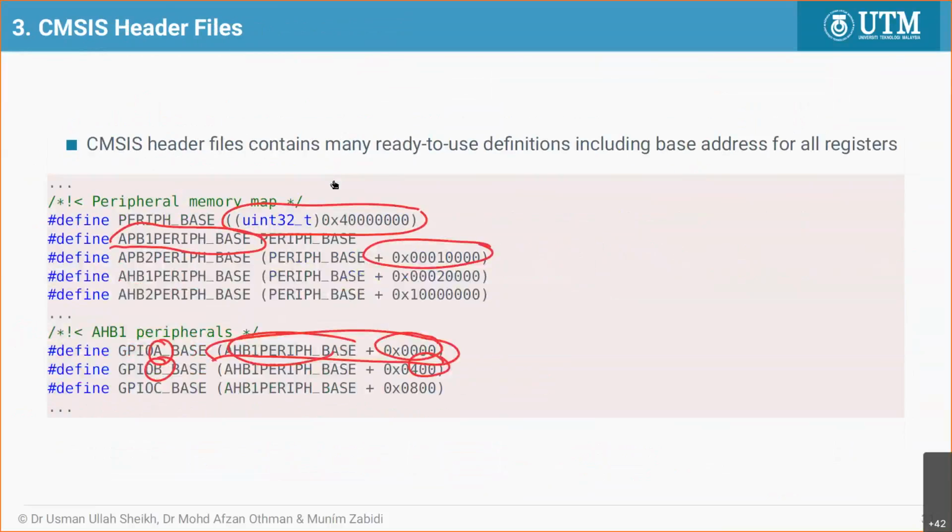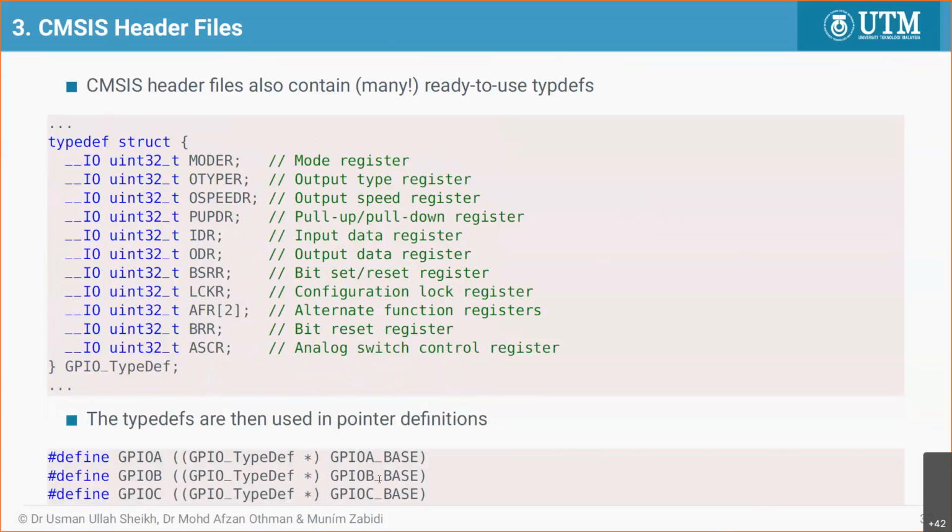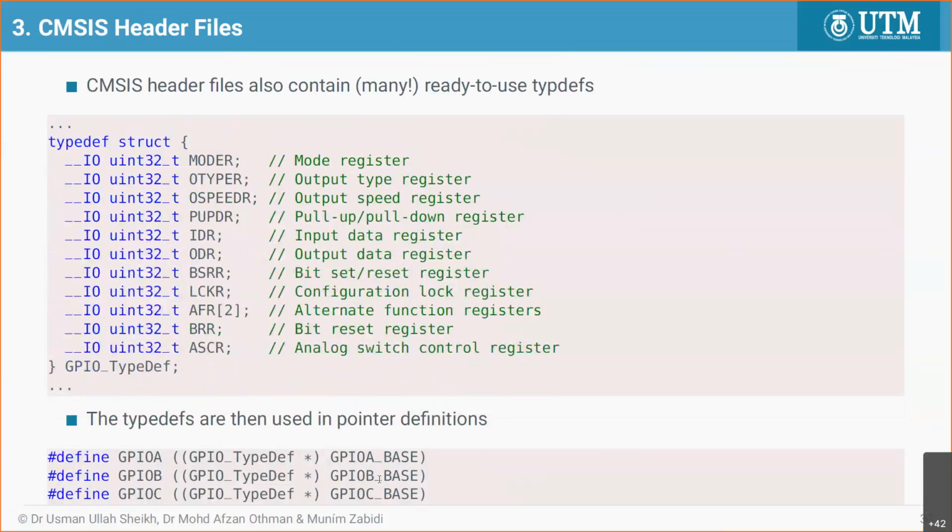That's reflected in this include file. So you can see here, they just say, okay, take the peripheral base address at 400. That you will get the base for B, and then of course inside B, there are other specific registers. So they don't put it here. It's a separate define, but now we use the struct.